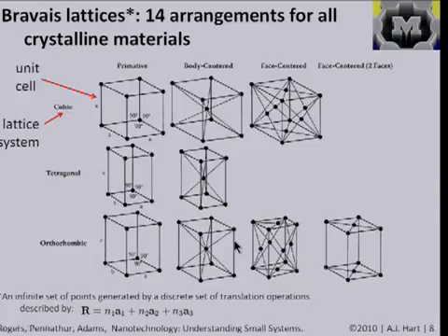You may have a large single crystal, something like a silicon wafer, where the atoms have a great degree of long-range order, or you may have a material that is considered polycrystalline, which might have a whole bunch of little small crystals that are all in different orientations. But if you get way, way down to the nanoscale, you're going to be able to identify each material as having a particular crystal structure.